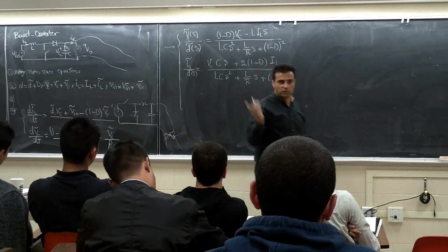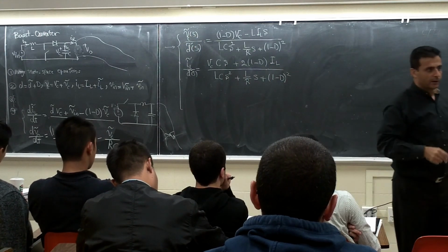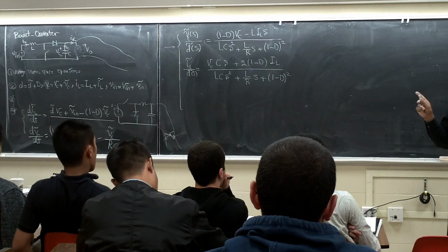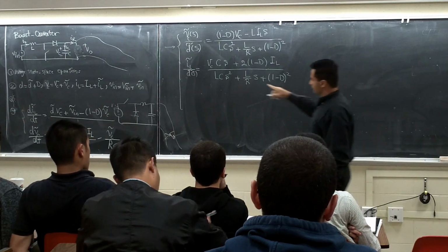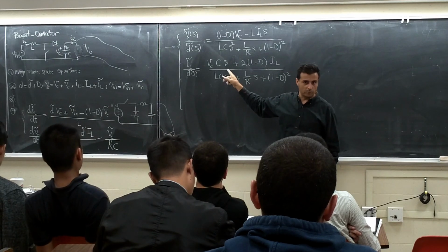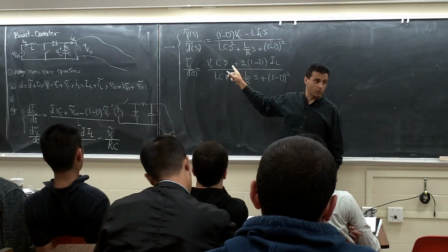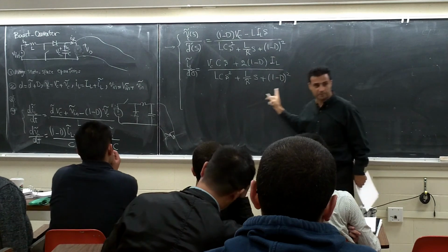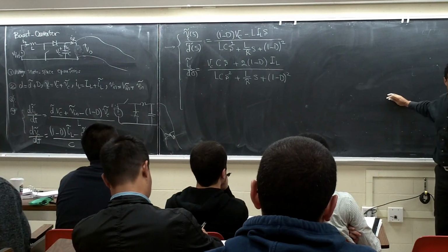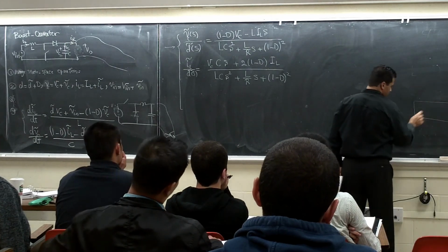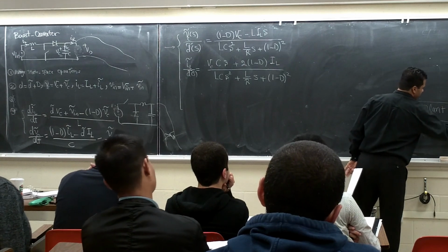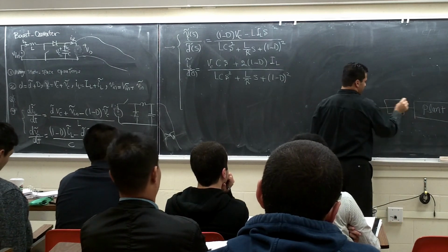But for some reason, for example, current mode for the power supply, or a solar panel, sometimes you want to control the current. So you go find this transfer function. Now, if you are going to replace your boost converter, use this transfer function. When I had those control loops, I see the plant here. If you look at the plant, here is going to be I, and here is the PWM generator.